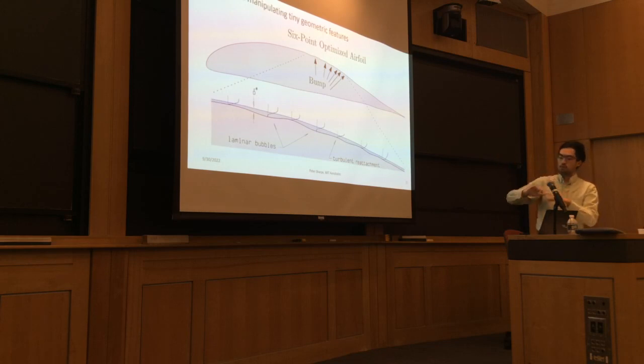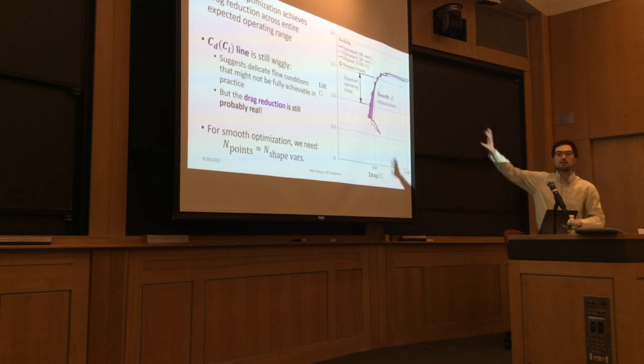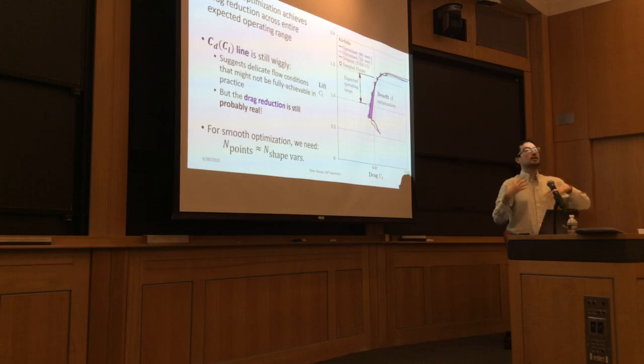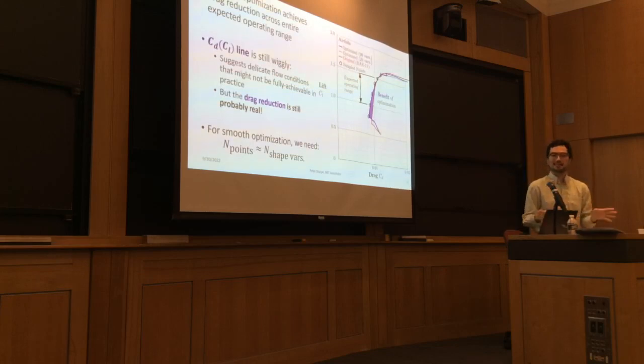there is probably, so if you decrease the number of degrees of freedom, so you didn't let the optimizer work at that small scale, you could probably fly these designs. And in fact, the 6-point design is a reasonable approach if you could build it, which is the one question about can you actually do that shrink wrap on the concavity. So, you know, this paper is a bit of a, it's meant to pump the brakes on optimization, but it's not meant to kill it.